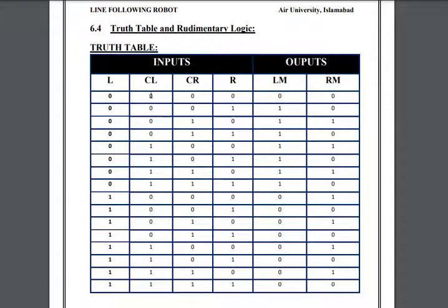This means in the sensor logic that whenever the light is reflected from a white surface, the sensor gives out 0, but whenever the sensor detects black, it gives out a 1. So for this first combination, there are 4 zeros, so all sensors are on the white. For my design, I have selected that in this condition both the motors should be off.